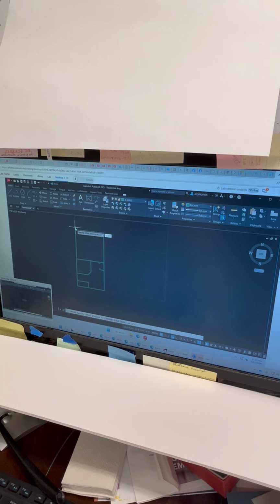Now I want you to trim out the lines that are in the middle, but here you got to be careful. I don't want to leave these on the east wall. I don't want to leave the little things here, so you want to put this east wall off stage, off the screen, and then trim those lines. Like that, okay?